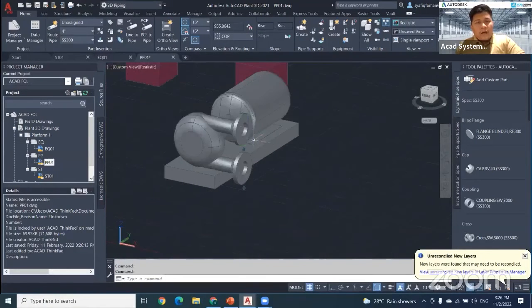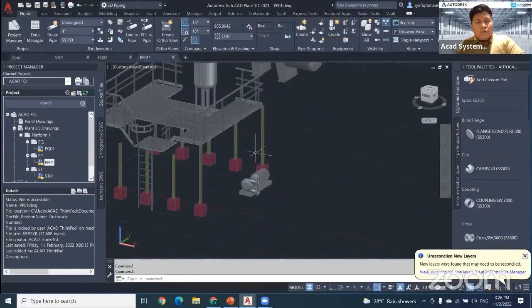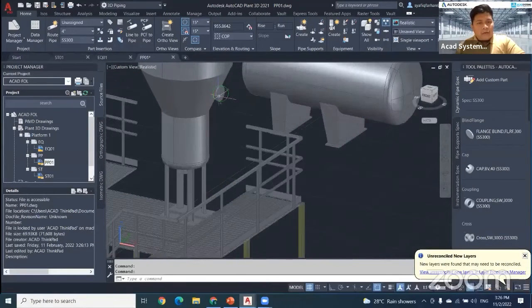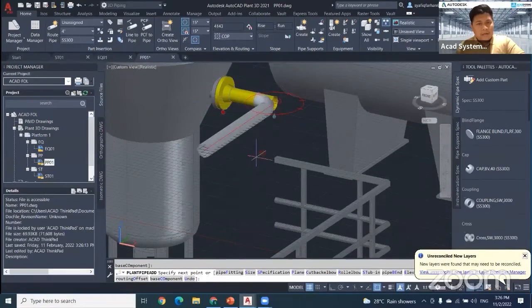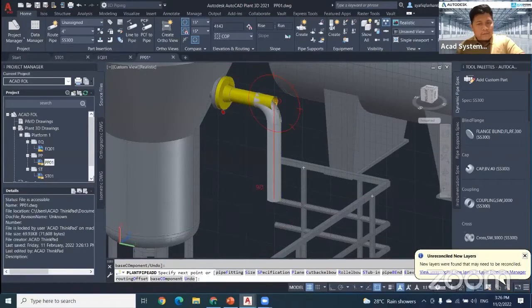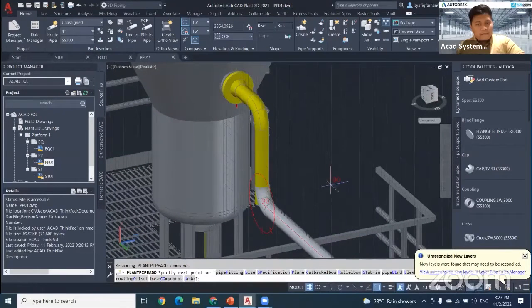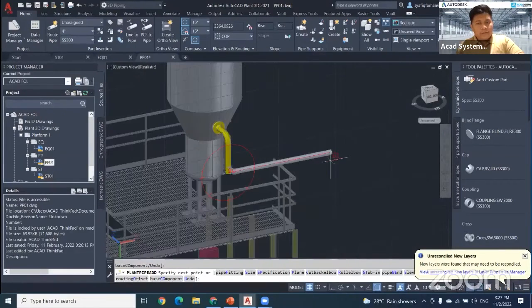Okay, so over here I can create a pipe. In this area, I know that I use 4-inch. So I just need to choose 4-inch, 300 pressure class spec, route a pipe from here, and then I can draw directly. Control Z, Control right click to change the orientation.